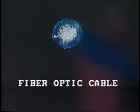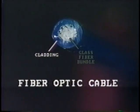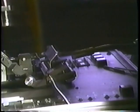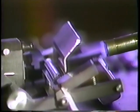Obviously, the inner surface of the fiber has to be reflective, and its surrounding cladding is specially made to prevent or at least reduce loss of light. An advantage of modern fiber optic communication is that the attenuation of signal, that is the loss of signal, is much lower than in other forms of communication. The fiber optic cable is made of glass or silica or a special plastic. It is very expensive, and so it must be handled with care during installation or repair. Special splicing techniques are required to join sections of cable.